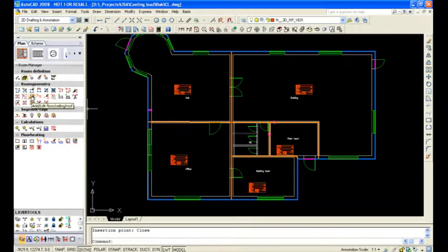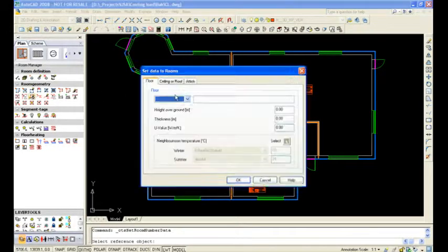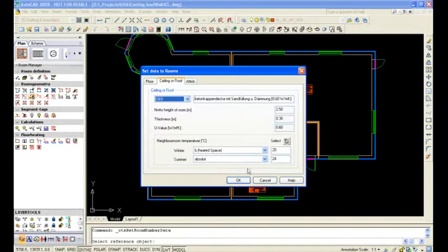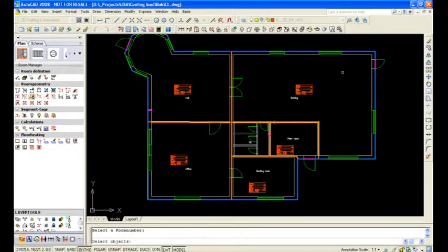We will select floor and ceiling assemblies in the C.A.T.S Commander. We can select from the database or edit the database if needed. Highlight the entire drawing interior. The color changes in the text block to yellow, indicating the floor and ceilings have been assigned. We will select the command Edit Room Number. We are adding all of our rooms to the cooling load calculation.